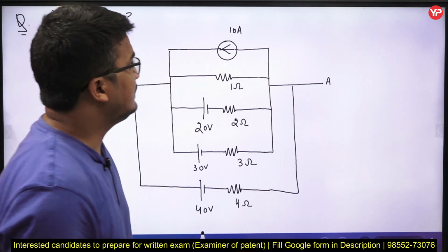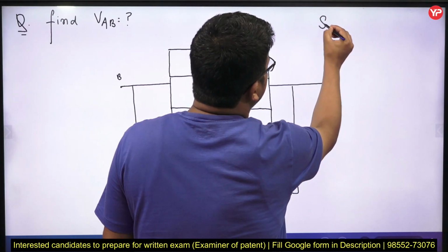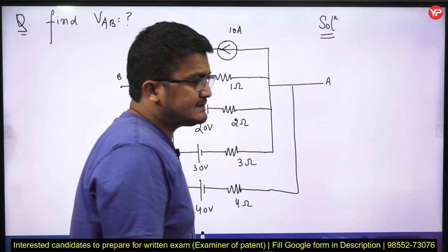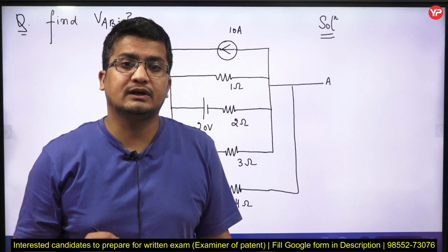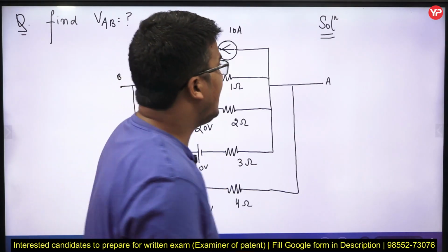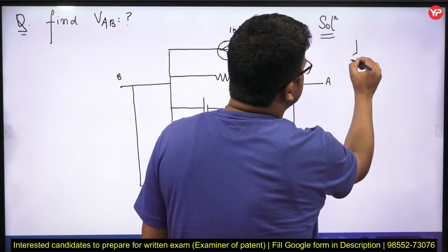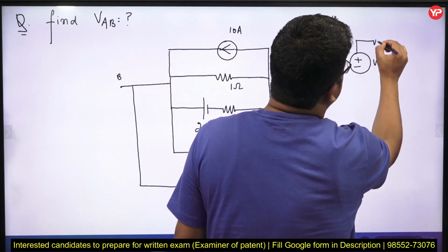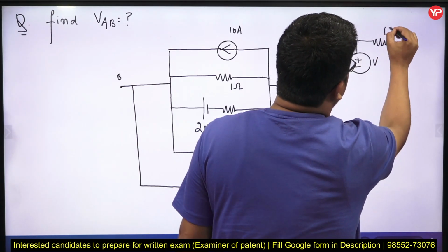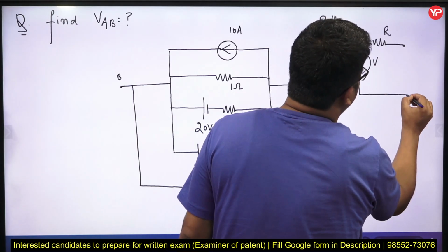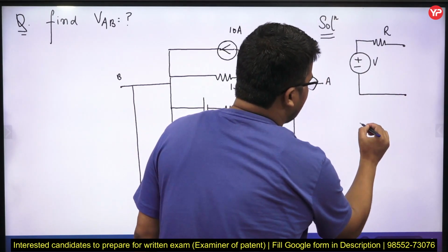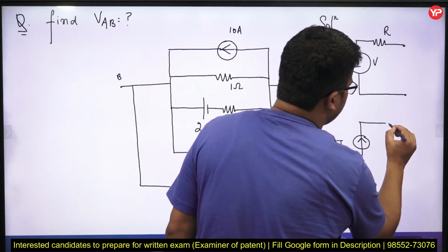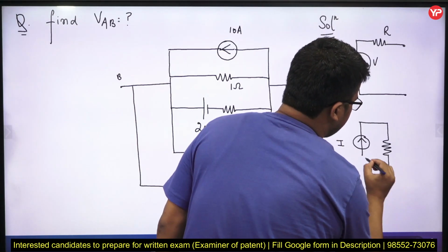As a basic electrical engineering concept, we represent a signal either in the form of voltage or in the form of current. For a voltage source we have the Thevenin equivalent, which is a voltage V in series with a resistance R. Similarly, if we represent our source with current, then we have the Norton equivalent, which is represented by some current I with its resistance R in parallel.